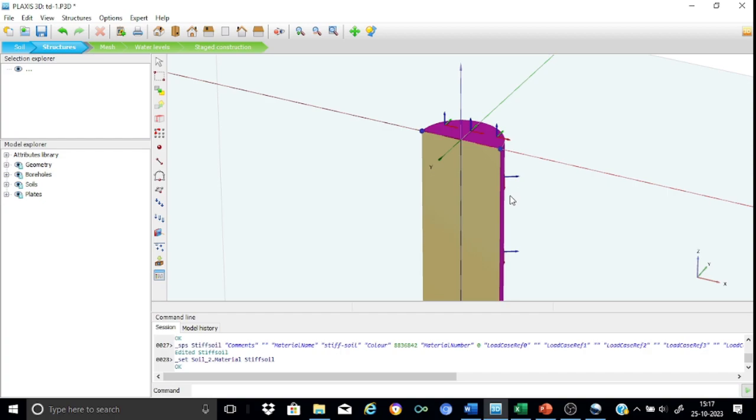Please remember that for this suction anchor we assume that the failure mechanism involves a rigid body motion of the entire suction anchor. Accordingly, we assume that the slip takes place only between the outside of the soil and the suction surface, and that there will be no slip between the soil plug and the suction surfaces. This means that we need to create only one positive interface for this case.